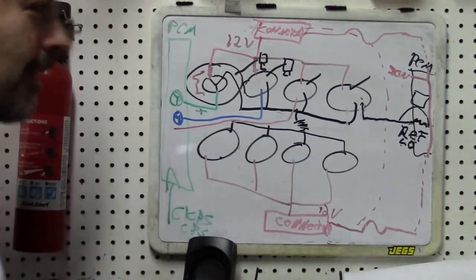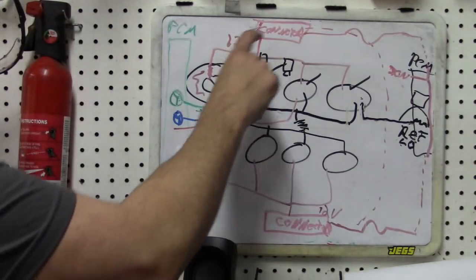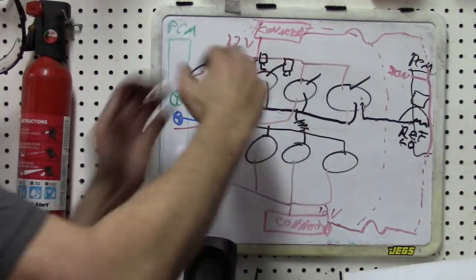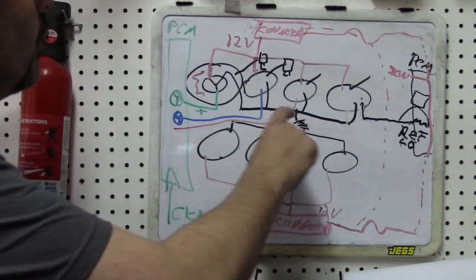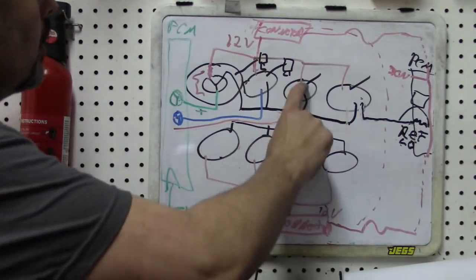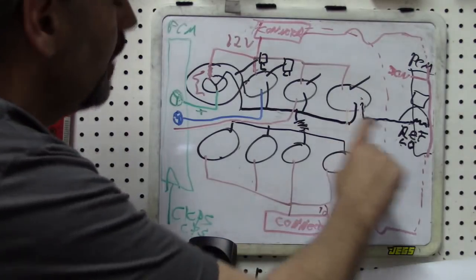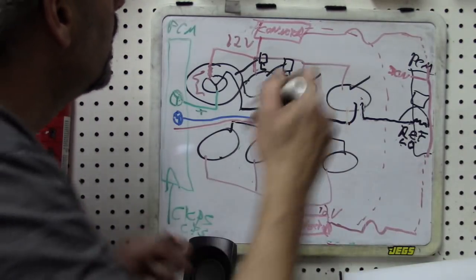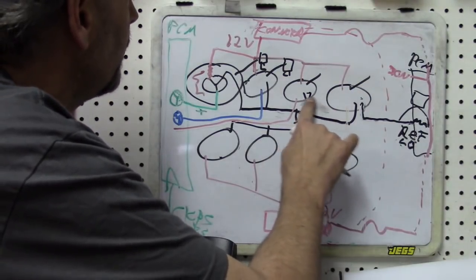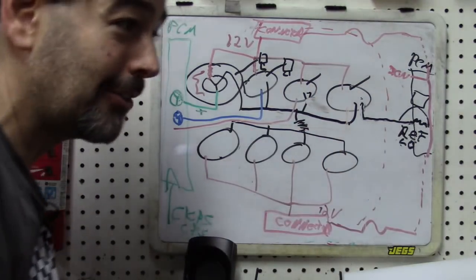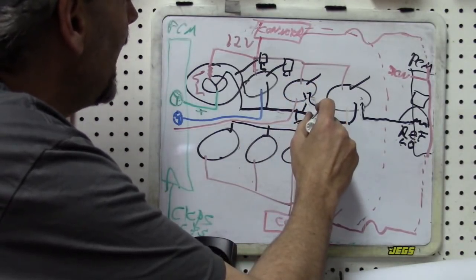Okay, admittedly my diagram is not quite as pretty and linear, but we do have the same things. We've got our 12-volt branched feed, we've got our branched shared ground, we have individual coil control to the transistors, and then we have the 4th wire on each of these. I wish I didn't draw it. I need more colored markers, I believe, for the more complexity that we're getting with our electrical videos now, don't I? But each one of these is also going to have the low ref.